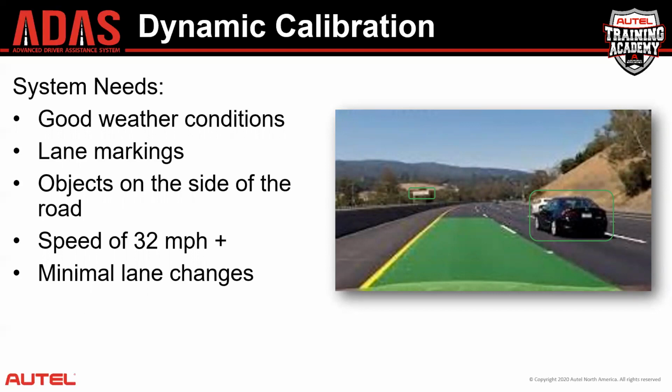And one thing that you really can't do is repair the vehicle, give it back to the consumer and say, because it's raining out or snowing out, I can't perform this calibration. Bring it back when the weather clears and I'll calibrate it then. That opens you up to a world of hurt, of potential liability in the time between when that vehicle left and if it ever returns.